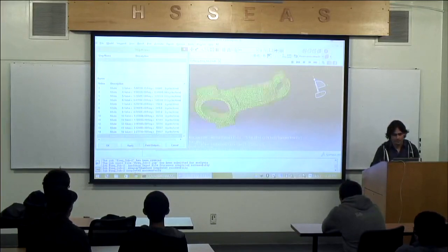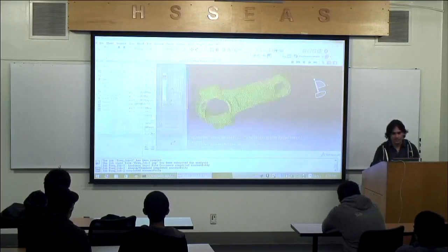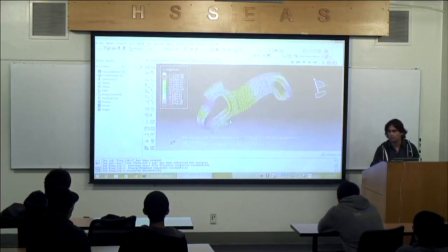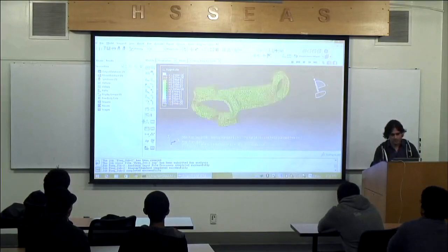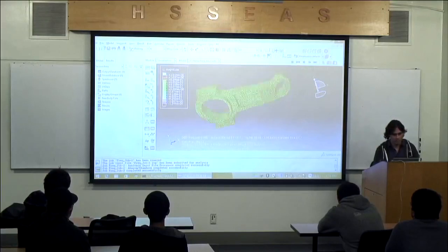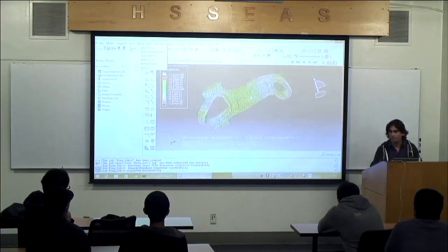All right. So this is how you can extract the frequencies for your solid model and extract the mode shapes. So all the information is here. You already saw how to animate. You can do it from the toolbox area, or you can go to the menu toolbar and select harmonic. Both ways you will get it. You can create a video and export it if you want to do it.